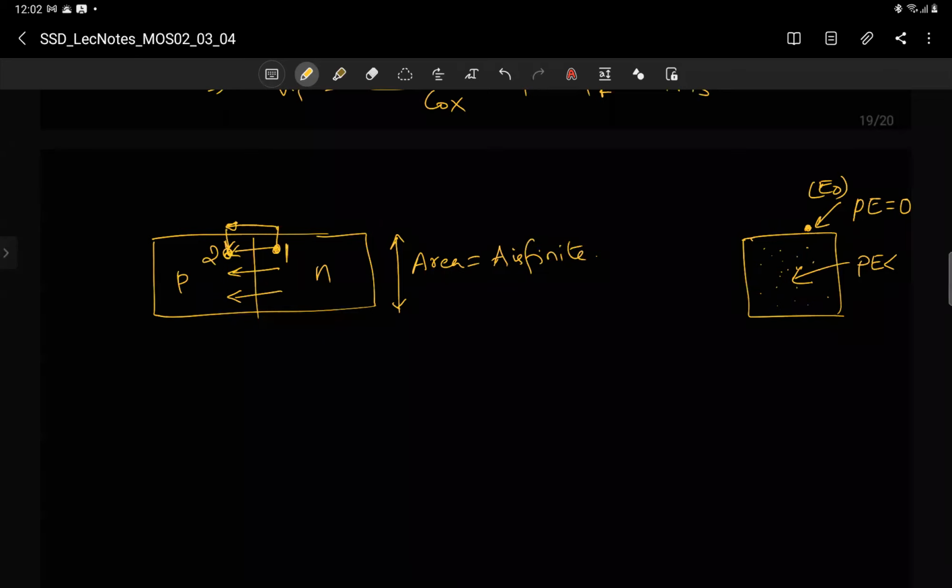Inside a semiconductor, an electric field can be there and you can have current flow. Even if you don't want current flow, you can still have an electric field, because drift and diffusion sometimes balance each other. So you can have an electric field inside with zero current in a semiconductor, because you can have a gradient, which causes diffusion current. Don't think a conductor always means zero electric field. That is only electrostatics, not dynamics or when current flows. Okay, sir.